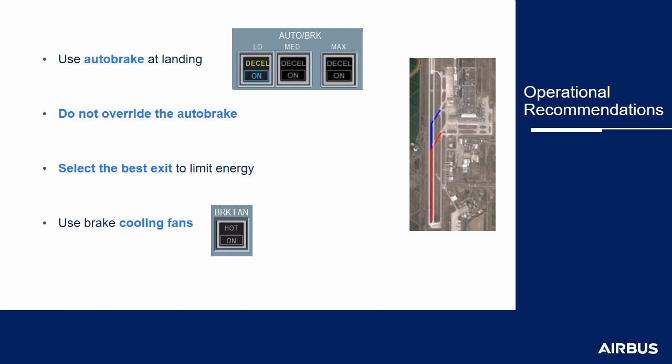As described in the standard operating procedures, use brake cooling fans if they are installed to facilitate heat dissipation and brake cooling. These brake fans will lower the time spent at high temperatures and therefore reduce the brake oxidation.